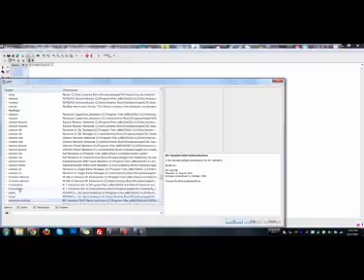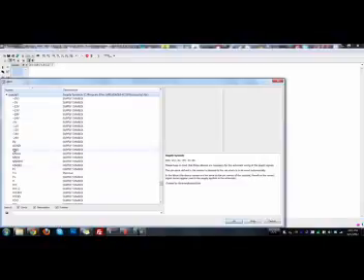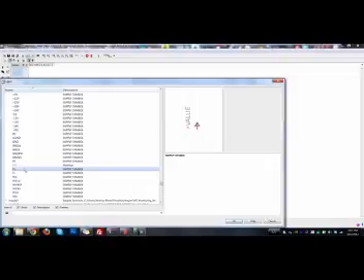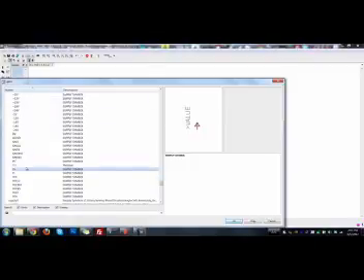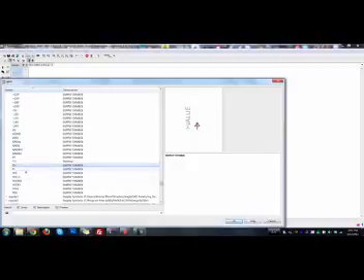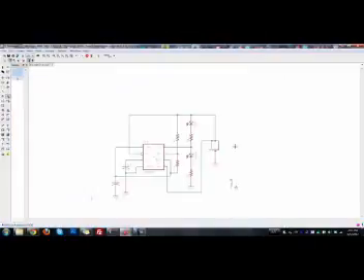If we go back to supply, again, I can just hit S and it'll take me to the S's. So we're going to open up supply, and we're just going to get a generic V plus indicator. It doesn't really matter which one you use. If you have a particular voltage level, you can pick that one. But we're working with a 3-volt battery, and I don't see a 3-volt one, so I'm just going to pick V plus, which is fine. You could also grab VCC. Actually, let's do VCC. So we'll grab VCC and put it up there for now.